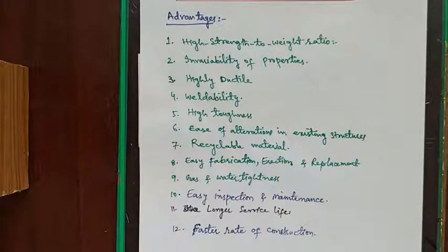Ductility is the most indispensable requirement in highly seismic regions. Therefore, steel is the better choice in comparison to reinforced cement concrete structures in regions of high seismicity. Another property of steel is weldability. Different structural elements of steel can be joined by welding, that is, it is weldable. Another property is high toughness. Toughness actually denotes the capacity of the material to resist fracture under impact loading. Both the strength and the ductility contribute to toughness. So, structural steel is a highly tough material and is capable of absorbing a large amount of energy.